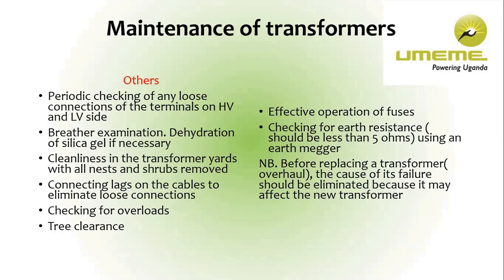So as a maintenance engineer on transformers, when you come and you find that these surge arresters have been breaking and making, then it means that that area is not a no lightning zone. And then you can ask the public, is this place always affected by lightning? The moment they say yes, you have to transfer the transformer from that place to another one.